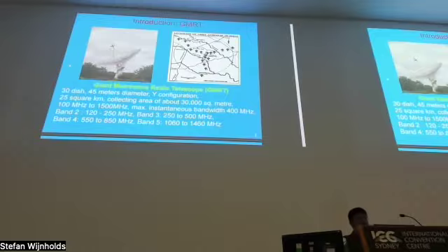So I'll give some introduction about the GMRT. GMRT has 30 dishes, 45-meter diameter antennas in a Y configuration, spread over 25 kilometers. The collecting area is about 30,000 square meters. The frequency of operation is 100 megahertz to 1500 megahertz, and the maximum instantaneous bandwidth is 400 megahertz. In 100 to 1500 megahertz, we have 4 bands: band 2, band 3, band 4, and band 5.